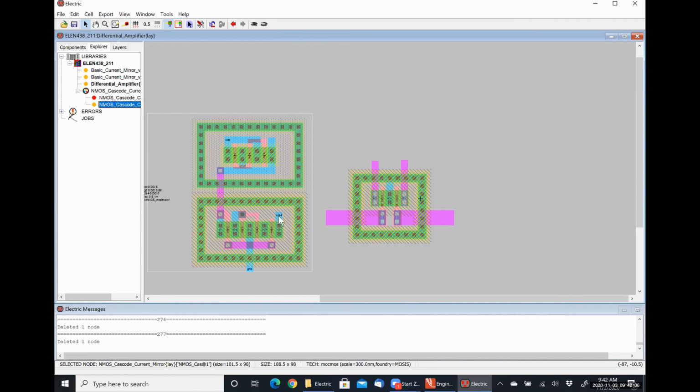So effectively what we're going to be doing is connecting where right here I have VDS4. This is effectively the output pin of the current mirror, and we're going to tie that to the grounding ring, and that's going to let us connect this guy to our current source.